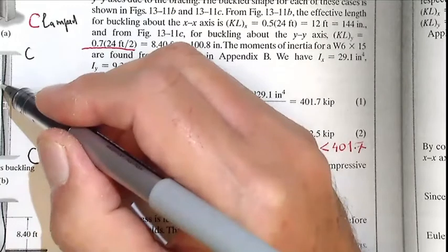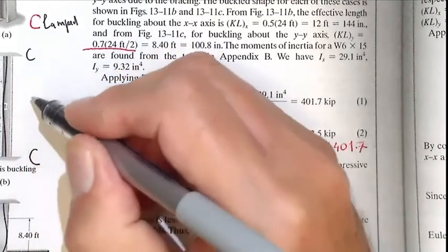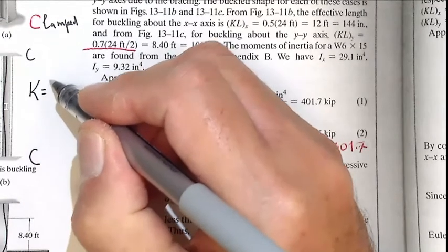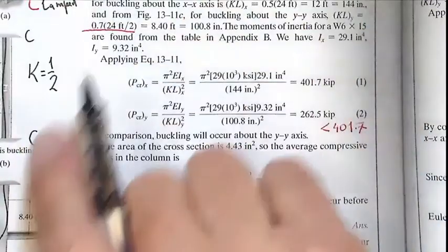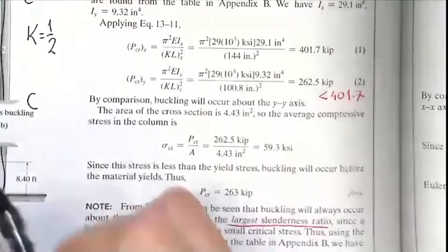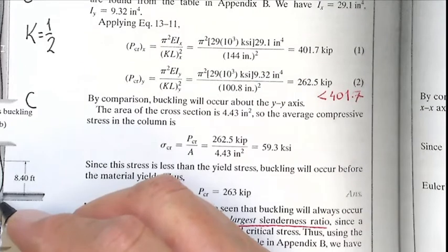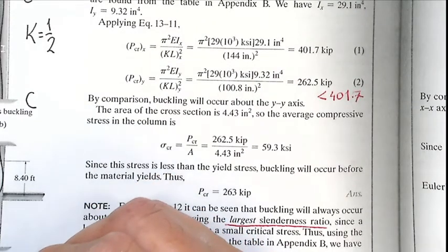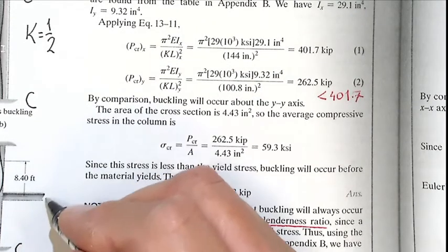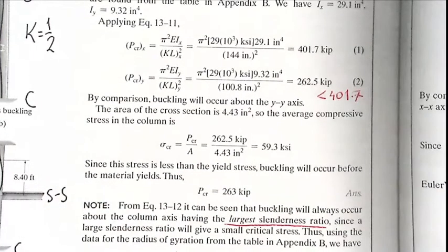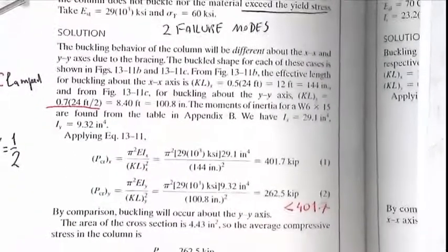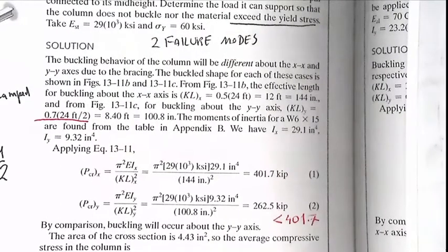Do you remember we showed that the effective length coefficient for a clamped column is 1/2. Now, in the other direction where the bracing occurs, we said bracing makes a simple support. So here below will be clamped, and here will be simply supported. So then it is 0.7, okay? So let us come back.